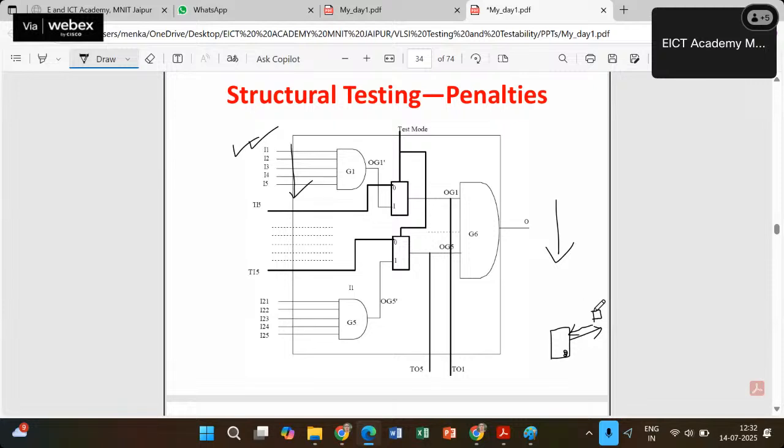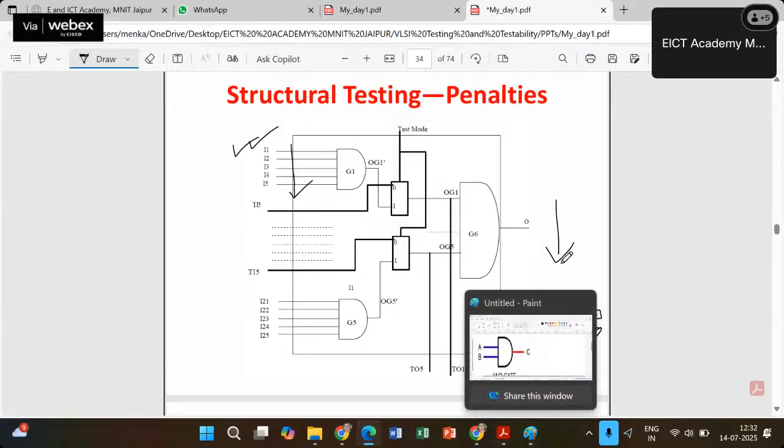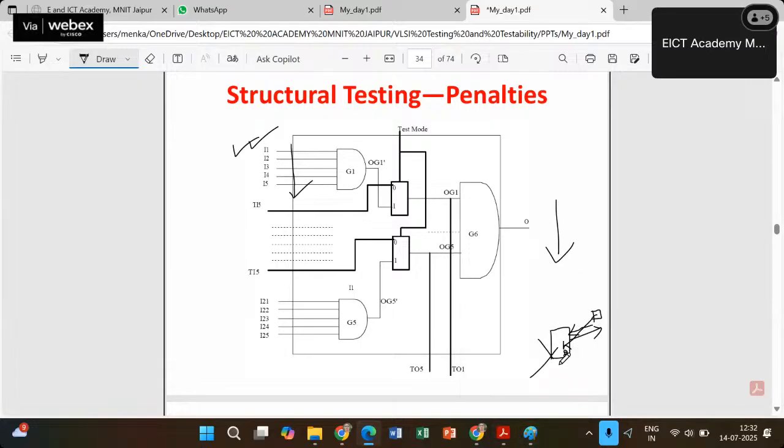If it is on, it means the power supply is going into the iron. And let's say now it is not working. So where is the fault? Definitely the fault is here. If the indicator is not working, it means the supply is not connected properly. So there can be a fault from this wire to the iron wire. It is a possibility. So this is the observation point, and this was the input point. The plug was the input point.